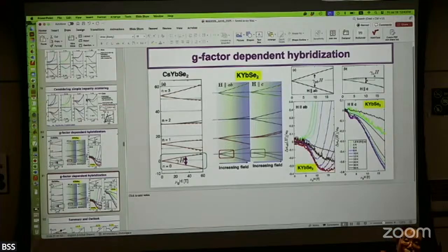Even though you put in your heat current, I squared R, you have a lot of radiation heat in random directions. It can scatter out and hit in different ways. If you don't take that into account, you will have a completely wrong thermal conductivity value. Radiation is one example, but there are many of those kinds of things.